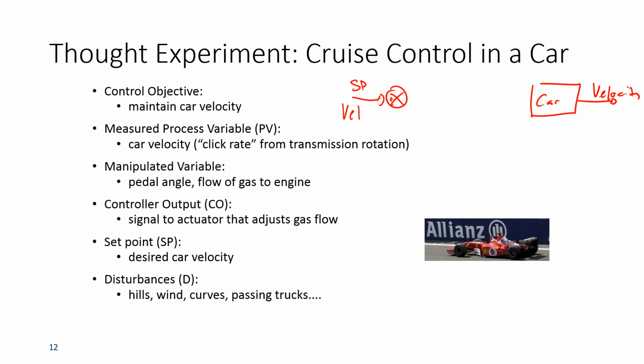Okay, so that's our actual process variable, and then we're going to have something that converts that velocity into a measured value. Okay, so this is our measurement device or sensor, and then this becomes the measured value of the speed. Now in cars, sometimes they have a thing within the transmissions or the rotational speed of the tires that infers the velocity. Okay, so this is maybe rotational speed or other things that are able to infer the speed.